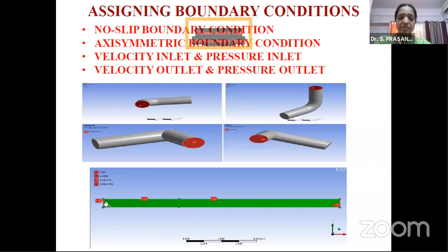So this is where the channel is. This is what we have initialized as the inlet, where the flow starts moving, and this is the outlet, as shown in the longitudinal direction, what we call the front view. In this direction, I have made this also a pressure outlet because the surface is open to the atmosphere. So pressure outlet, we have different boundary conditions here.